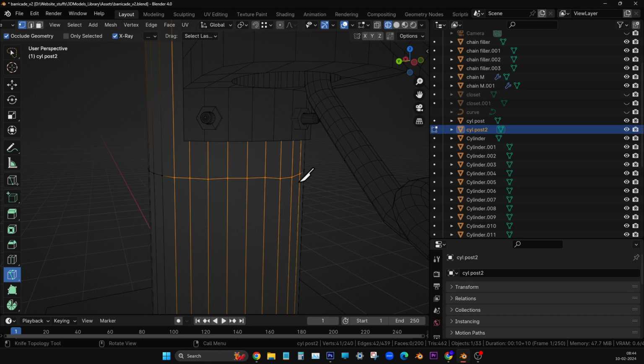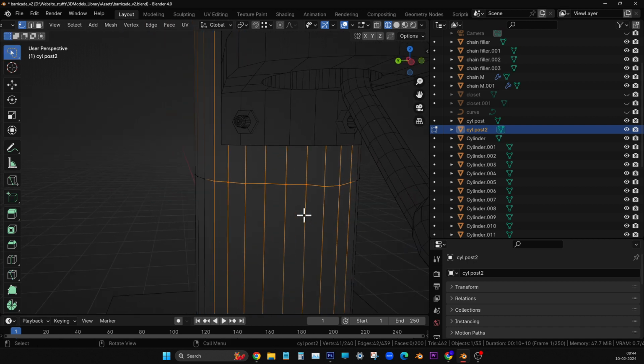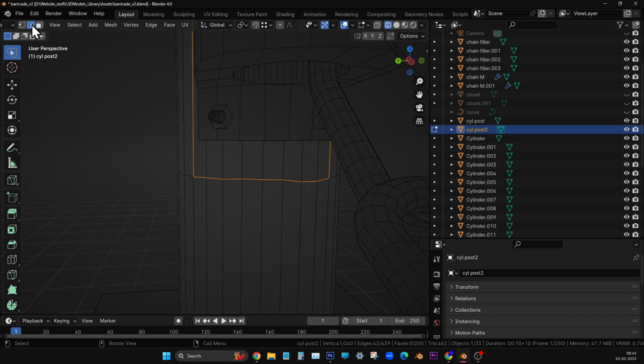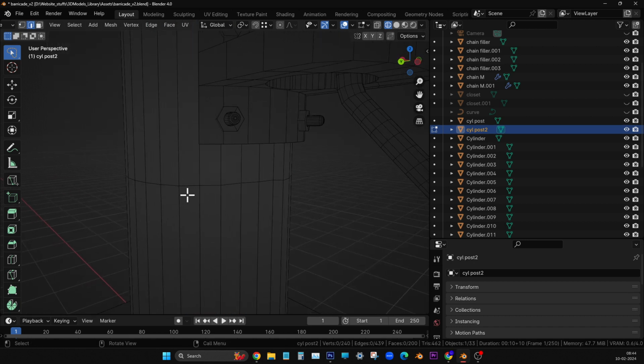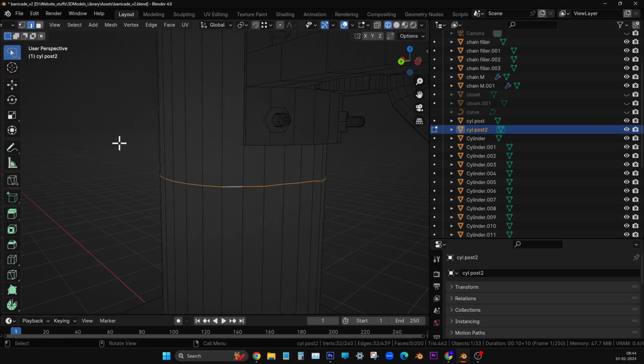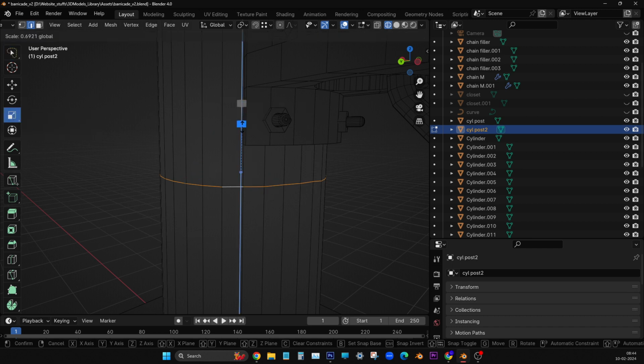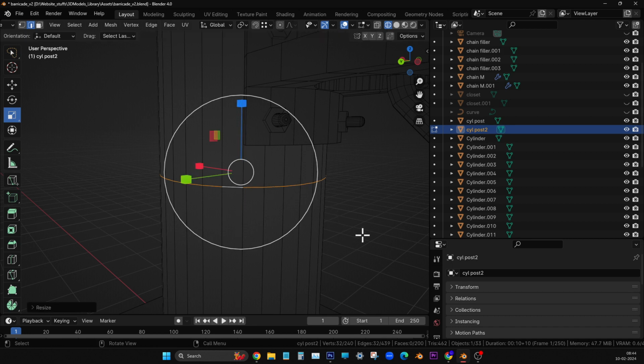or any other tool whatever we used just now, and if we feel no more use, then we have to go out of the tool immediately. I'm pressing W, and I have gone out. Now I will switch to edge mode, press Alt A, and select the edge loop cut, then choose the scale icon in the toolbox, and scale down in Z completely, special manipulation 0. That's all.